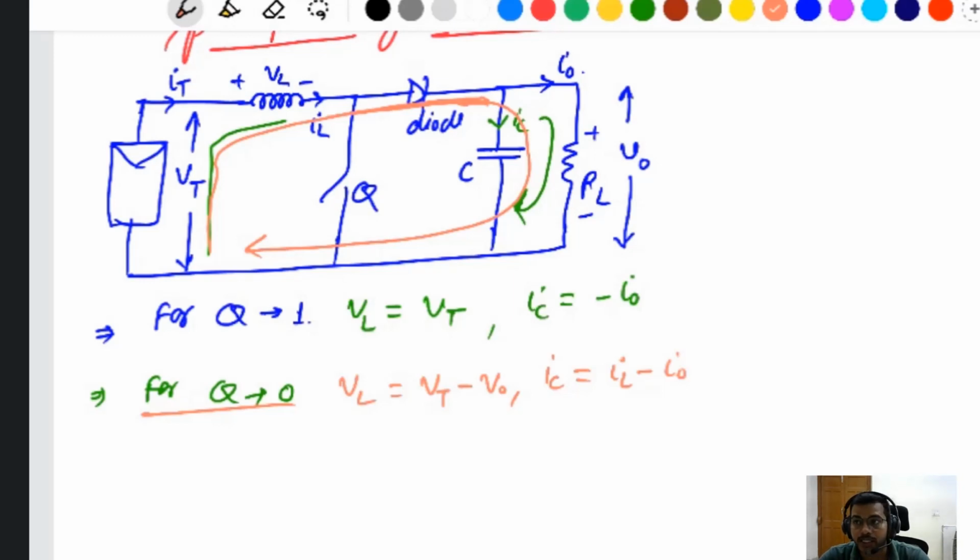The same thing applies to the capacitor. This is known as current-second balance. It means the charge of the capacitor should be maintained over the charging and discharging time. That's why the average voltage of the inductor will be 0, and the same for the capacitor: the average current of the capacitor will be 0. To operate the inductor and capacitor in a DC system, you should maintain that.